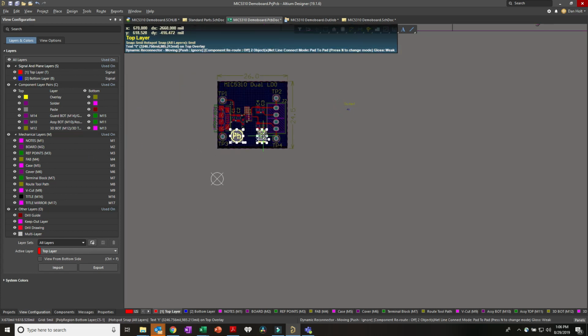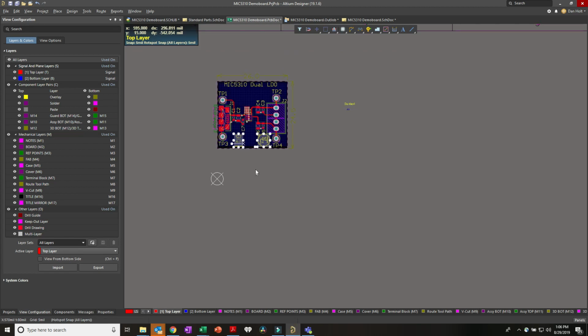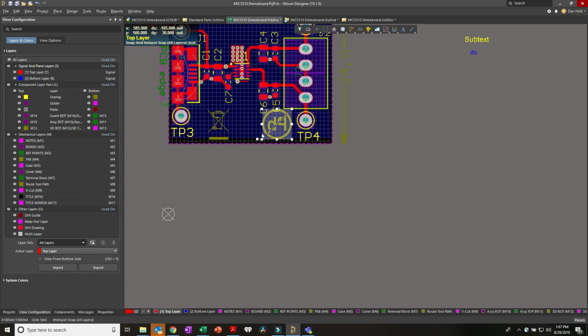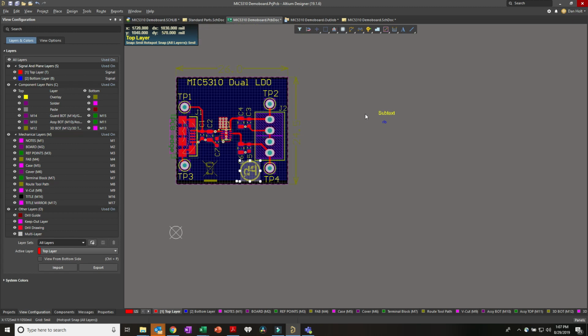Now if I press L, it flips layers. So by just clicking L just now, it flipped these two symbols to the backside. So you see there a dull yellow, which is a backside solder mask, or silkscreen layer. This stuff we can just get rid of. Just drag this down here.